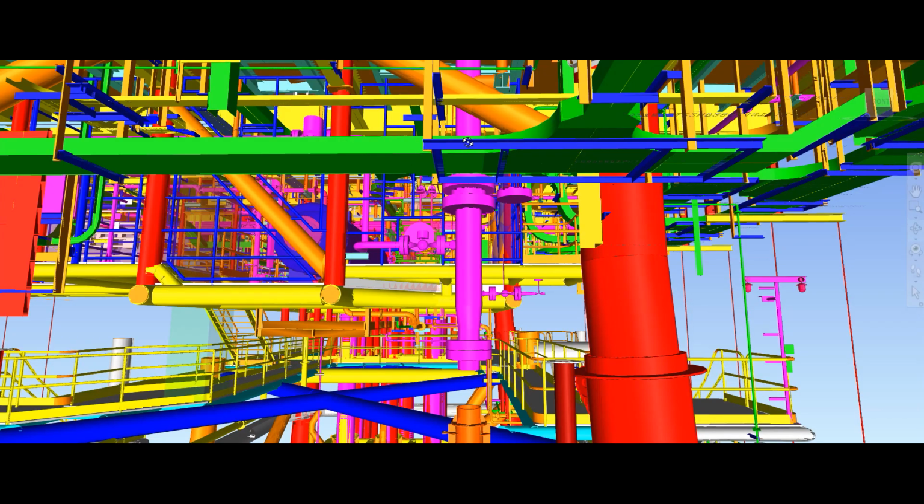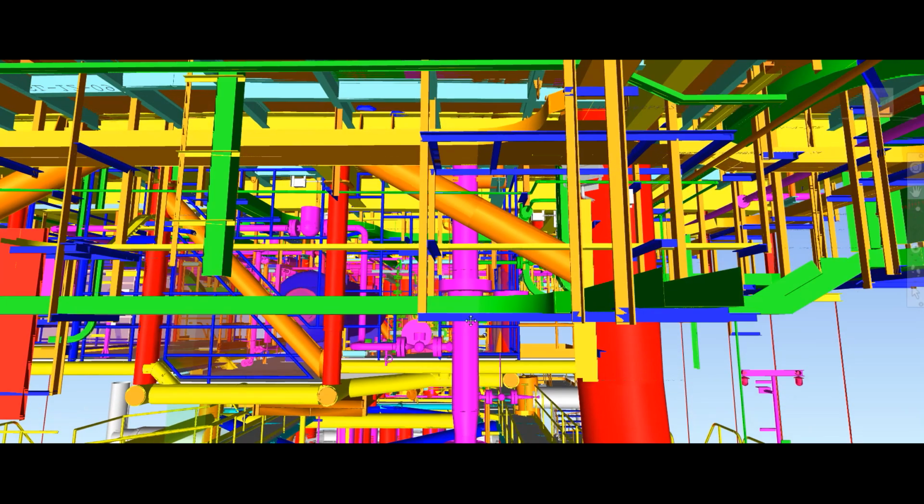So the production header, you can see this pink line. In some locations there is no launcher, but in a few platforms we have a launcher. So this production platform is connected with the launcher, and from the launcher the line is coming and connected with this dropout spool. You can see this is the dropout spool, and here in this platform there is no launcher, so that's why the line coming directly from the production header is connected with this dropout spool.